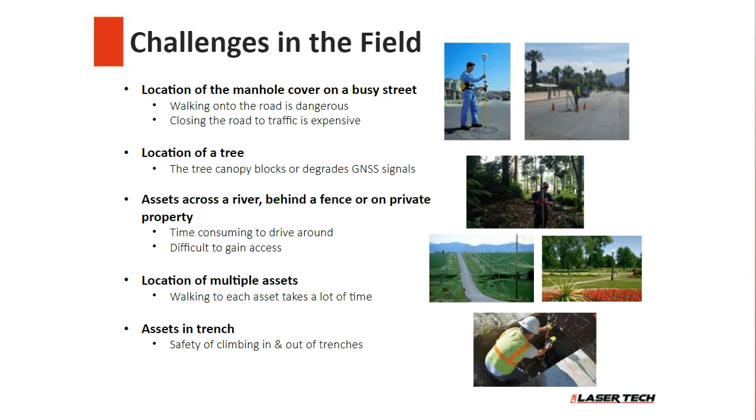Or you have to position something underneath tree canopy, maybe not visible from that drone flight that you flew, visibly blocked by it. Or just access issues. It's across the river on private property, where it's just going to take too much time and be inefficient to actually occupy the point.